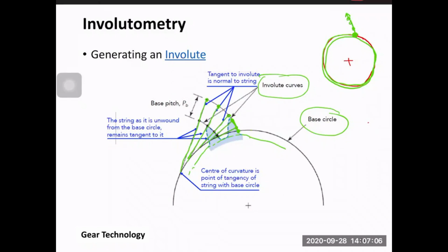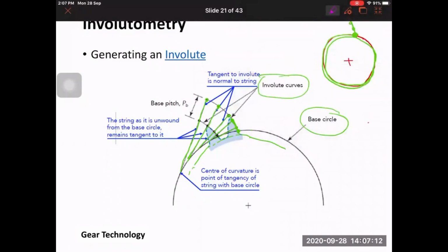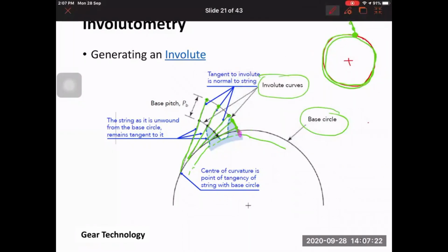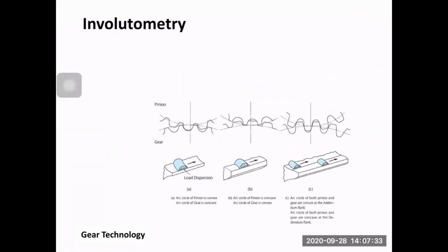So this part here, between these two, is the non-involute portion. You will understand why I'm stressing this at the moment. It is quite important, but later we'll talk about this, okay? So you know that the involute curve starts from the base circle. You should know that, okay? Right, so other involute profiles could be a part of a circle, for example.